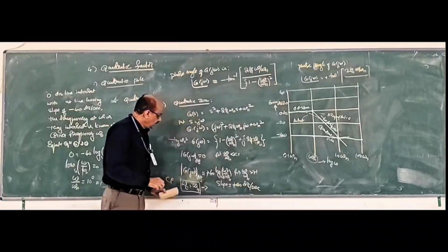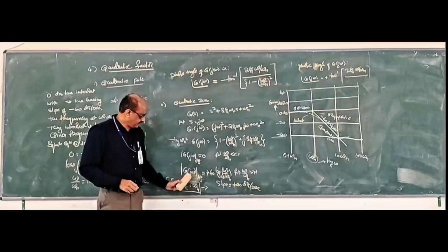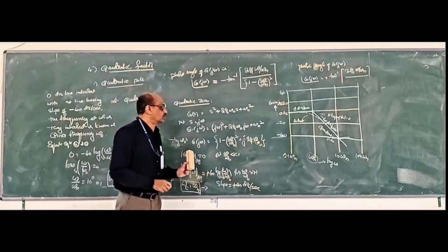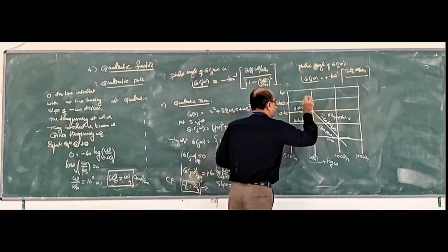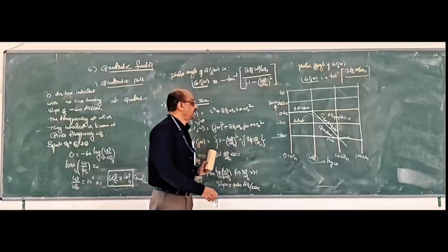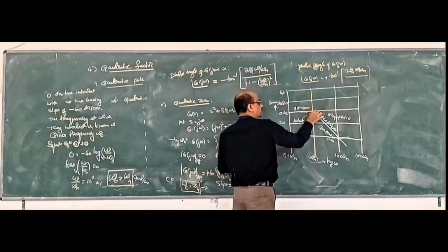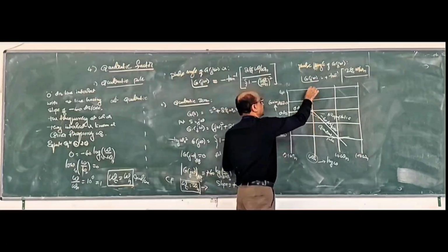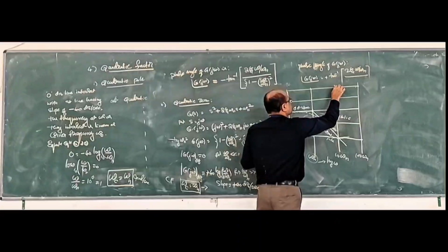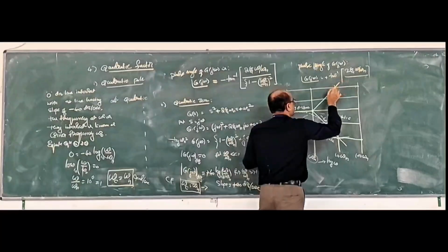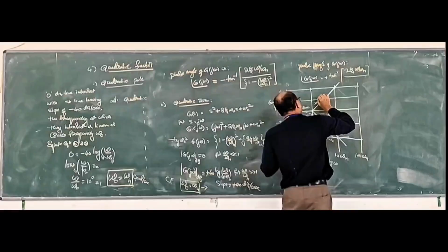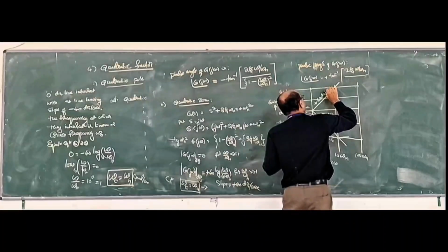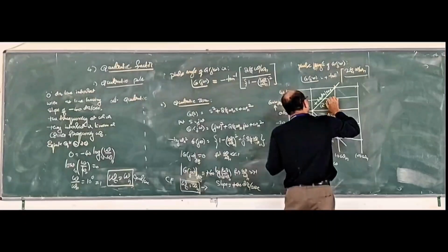Next, the zero, in other words, it is having the corner frequency omega c equal to omega 1. 0 dB till omega c equal to omega n, again till this point. It has plus 40 dB per decade. So take plus 40 from this point. Plus 40 is this. Mark that one. Go plus 40. Then 10 times is this. Joining that gives you plus 40 dB per decade. Write on that plus 40 dB per decade. This is your quadratic zero.